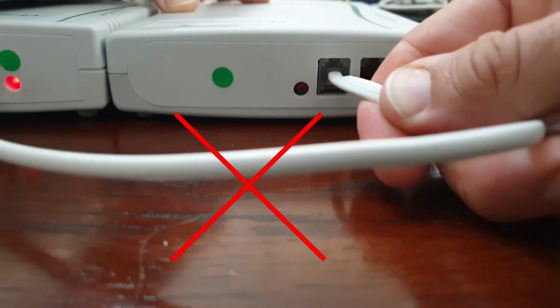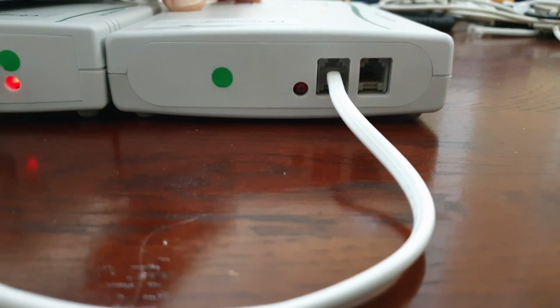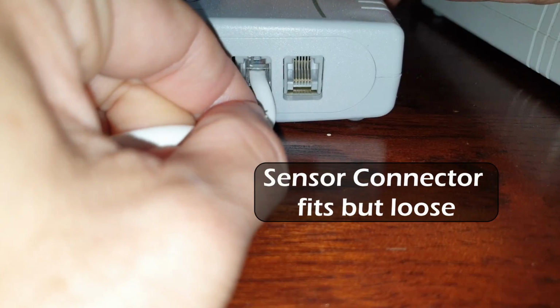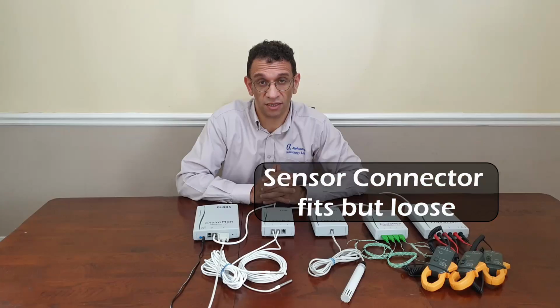This could be a damaged cable or connector, or it could be that the cable had been pulled too many times, causing the cable to lose contact with the crimped connectors. Other issues could be a bad crimp or the use of a wrong connector. As we said before, some of the EnviroMon sensors use a 4-pin connector, which is narrower than the EnviroMon network connector. It will fit into the EnviroMon network port, but will be loose and will make and break contact. Now I'll cover another video about crimping connectors later on.